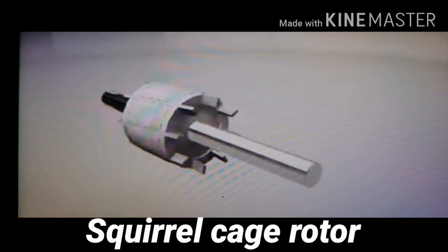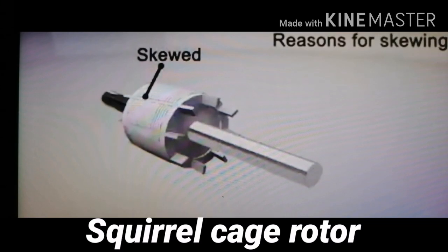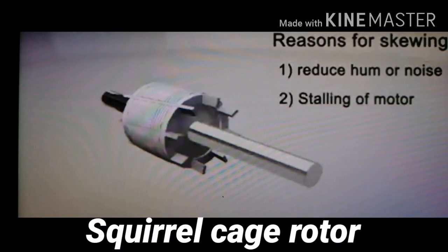This forms a permanently short-circuited winding. These bars are a little skewed due to the following reasons. Number 1, hum and noise reduction. Second, to prevent stalling of the motor. The entire construction resembles a squirrel cage and hence the name.